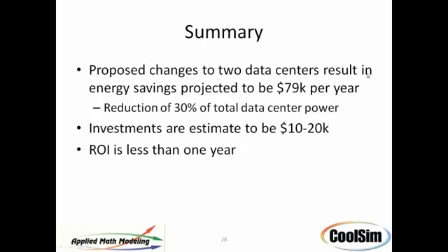Maybe we can say, Paul, that it's not unusual to see savings in the range of 70 to 80%. It's a pretty incredible impact. They can be very high. And I think, Magnus, you'll agree the reason for that impact is you slow the air down, you get a higher return temp, and you get better efficiency out of that unit. Yeah, this 70 to 80% is really just on the fan cost because of that near cubic relationship.